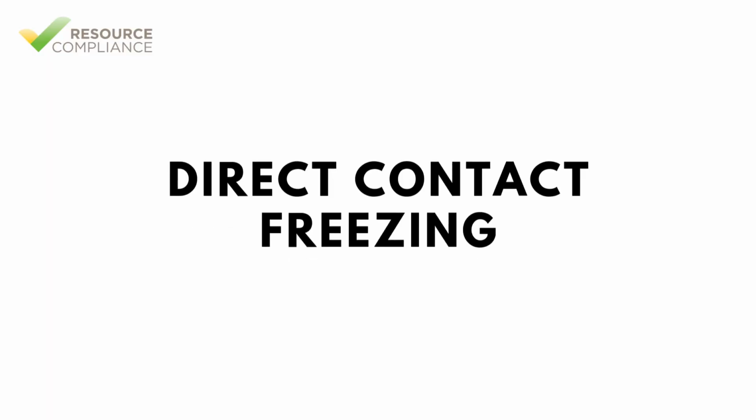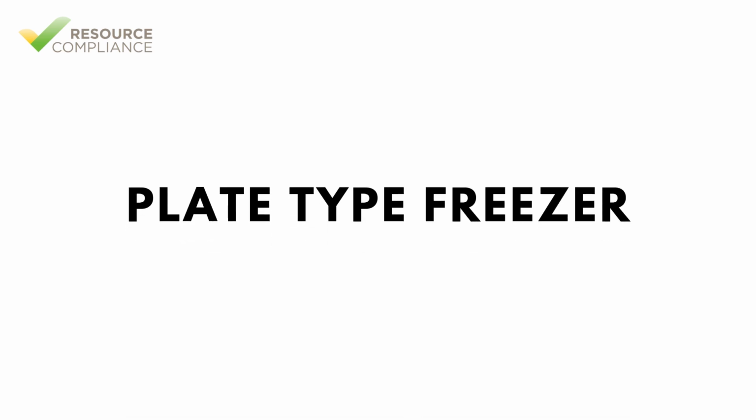Direct contact freezing is less commonly employed than air cooling or fluid cooling, but can be highly efficient. The plate type freezer is the most common type of direct contact evaporator. A plate type freezer is a specialized evaporator used to rapidly freeze products by placing them in direct contact with cold metal plates, which are chilled by refrigerant.